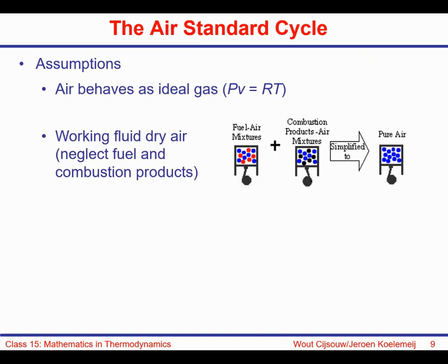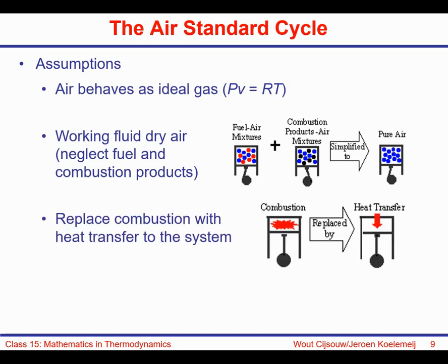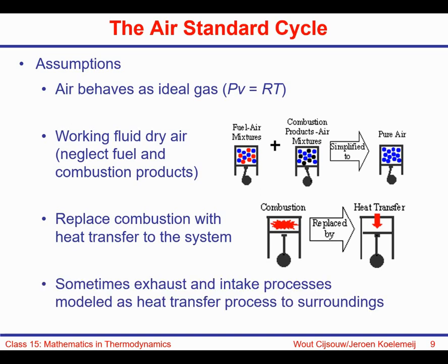The working fluid is actually dry air without any other contents. So we ignore that there may be fuel or combustion products. So that's a simplification. And we replace the internal combustion with some sort of heat transfer mechanism. And sometimes also the exhaust and intake processes are modeled as heat transfer mechanisms too.